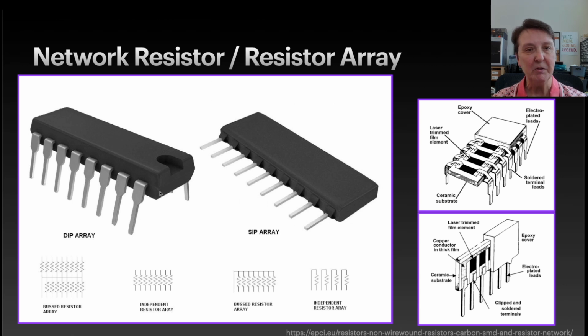I've also seen people use these in projects, the dual inline package arrays. These are maybe easier to understand: inside, in between 2 pins, you have a resistor. Basically, you see it this way in an electronic diagram. When you get some, you have to know how it's set up so you know how to wire it. Different ones work in different scenarios of how you're going to do your wiring. But in the case of our LED bar graph, the ones I have here are going to work pretty well.